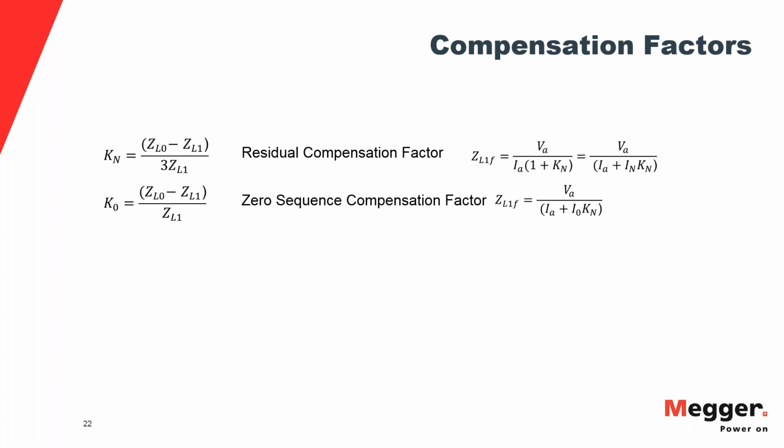And so I have another question. I don't know if we have a great answer for it yet, but how can we have zero sequence impedance value accurately, considering soil resistivity for a line to ground fault or two ground faults? Oh, there are so many methods out there, and that's one of the reasons why you don't use crisp values in distance protection.